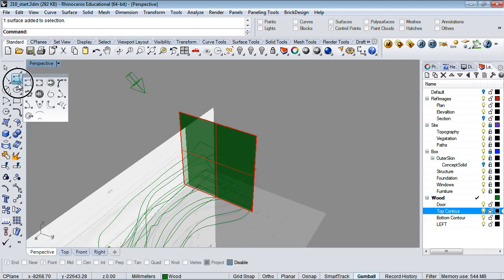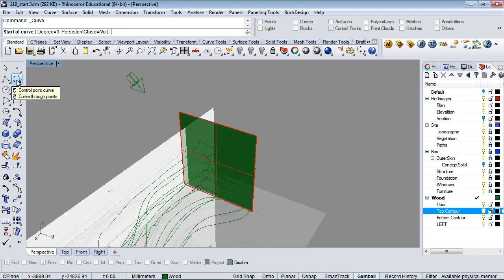And that could be an option, but what I've found is that when you do that and you're drawing an interpolated curve, sometimes the way it wants to generate that curve starts to be really wonky, because it's actually trying to calculate on the surface. So sometimes you end up with really crazy, hard to control curves. So that's why I prefer to work on the C-plane, creating a construction plane, a C-plane.